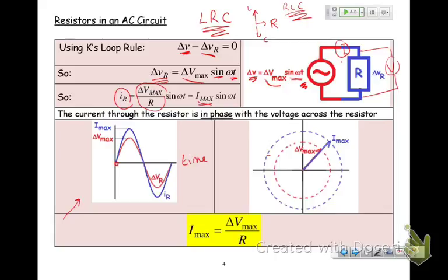And what happens is these guys kill you, and it's got a minimum there, and it goes back up again. So the sum looks like that. And there's a sweet spot where you have the lowest resistance associated with these components. And that is the tuning frequency for your circuit.